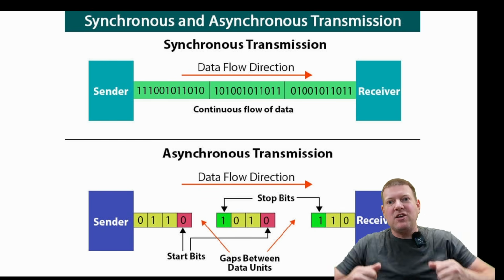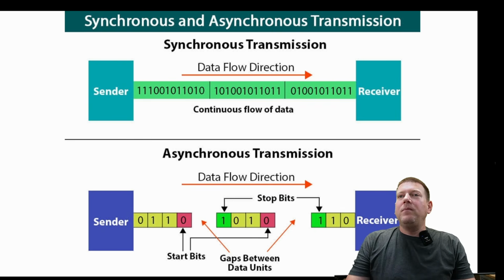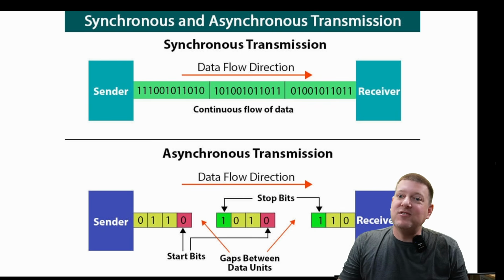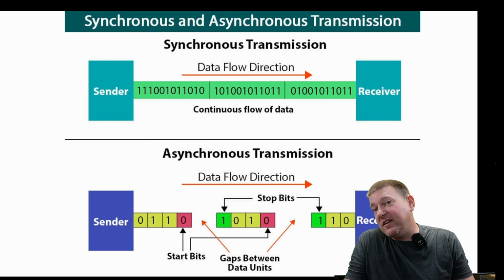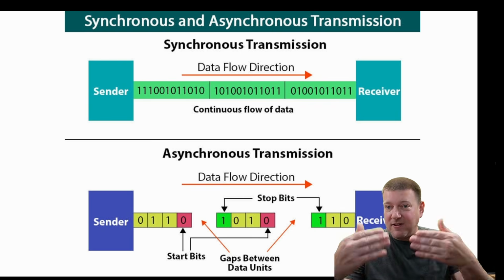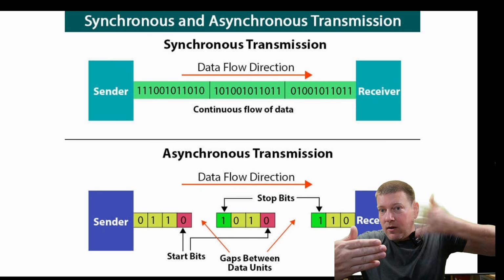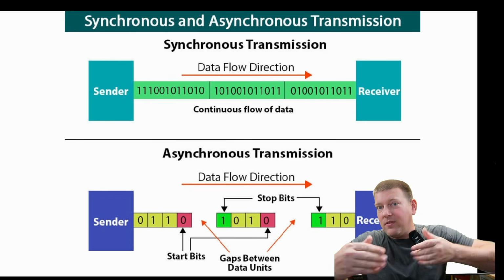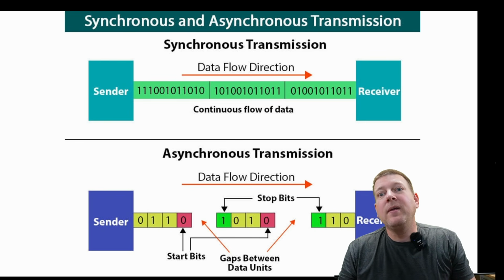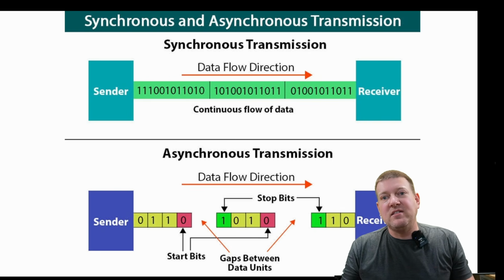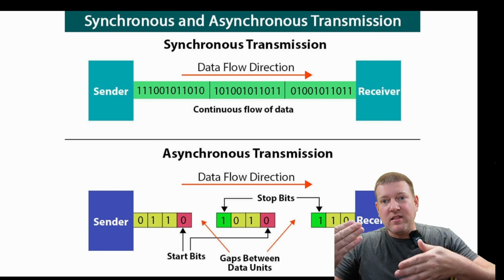And they handshake, right? Well, with asynchronous, usually you have to set the baud rate. It's not normally detectable, or if it is detectable, you want to make sure that it's configured correctly, because if one's talking too fast, it's going to be gibberish. So with asynchronous, it's very important that we get the same baud rate on both devices. That way they can talk.